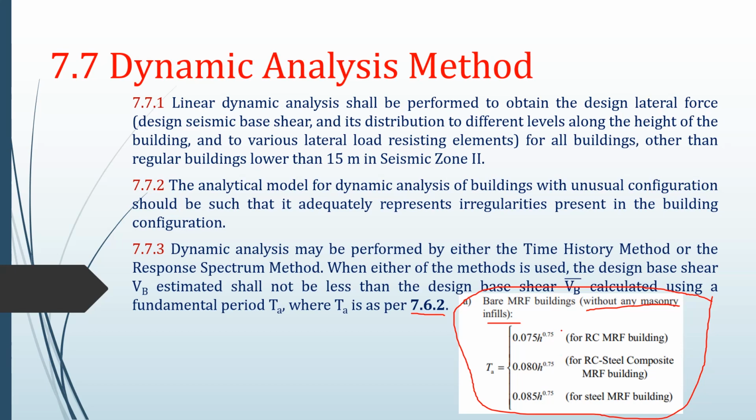If you remember, we used the formula 0.075 times h to the power 0.75 for the time period calculation of our reinforced concrete moment resisting frame building, where h represented the height of our building.